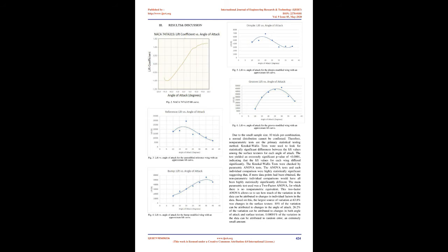There was a longitudinal groove on each of the reference lines starting from the leading edge of the wing and ending at 90% the chord length. For the bumps and dimples, one of either was placed along each line at a distance of 5% of the chord length from the leading edge of the wing. The radius of the surface textures was proportional to the chord length of the reference line. The dimple/bump radius was 5 cm for L1 and 6.8 cm for L2. Similarly, the groove radius was 1.57 cm for L1 and 2.14 cm for L2. These values were calculated based on a proportionality statement in a prior study.